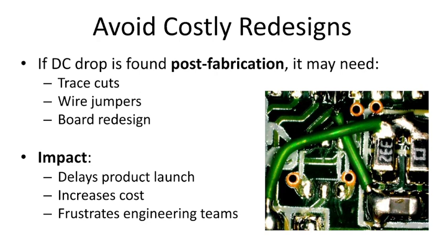In this case, just for the sake of improving the flow of current, they may do some jumper connectivity from here to here, because the path from here to here on the PCB trace, let us say there is some PCB trace like this, is narrow and doesn't get proper current, with a trace of, let us say, some 5 mils. Then what they do is they come with a wire later which has like a 20 mils diameter, and it is going to carry this current.